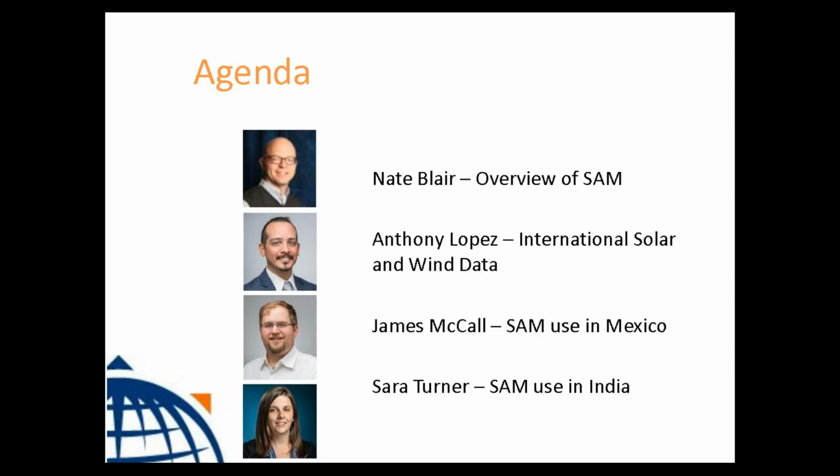We do not anticipate the PSM or NREL's model being used north of 60 degrees at this point. We use the GOES satellites, the geostationary satellites, for the PSM modeling. Once it gets above 60 degrees north latitude, we get too high of a sensor zenith angle and our models become a little erratic. So that's why we cut it off up there, and we don't have any plans at this point to go north of there. For those in Canada, NRCan, Natural Resources Canada, does have some information you can use. And if you're interested in Alaska, there are some older station data sets provided through the NSRDB that you can check out as well.